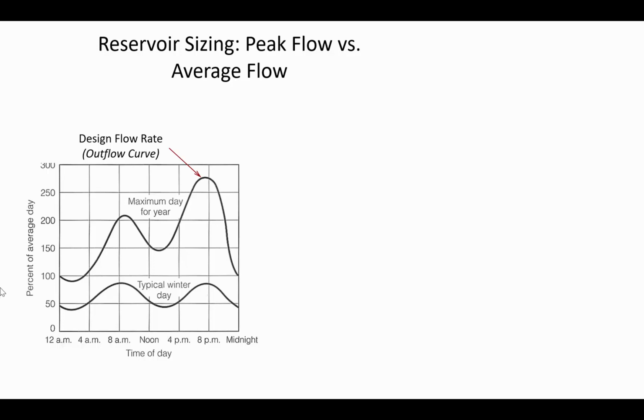And so what we are seeing is that there's some maximum for the day, and we know from your demand estimation summary sheet, at the very bottom of that summary page I asked you to write all your numbers on, it says what's the demand for the whole network. And we're saying, by definition, we're going to tie this curve to that peak.